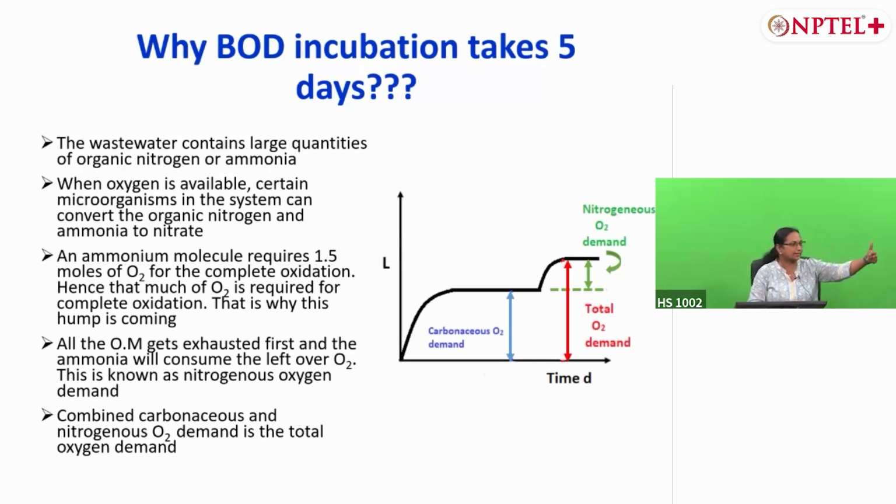The second condition I am telling is the consumption rate should be a minimum of 2 milligram per liter, because we are doing a lot of dilution, and in the BOD, any wastewater you take will have reduced inorganic compounds and other things. That also may be consuming some oxygen. So we don't want to overestimate the oxygen, and we want to make sure your dilution is correct.